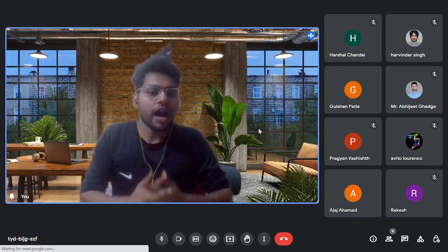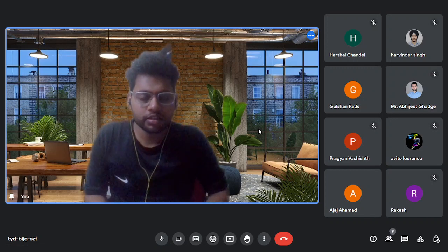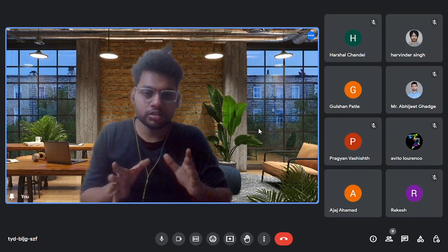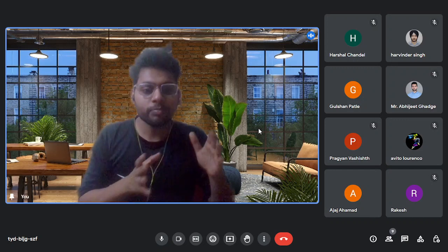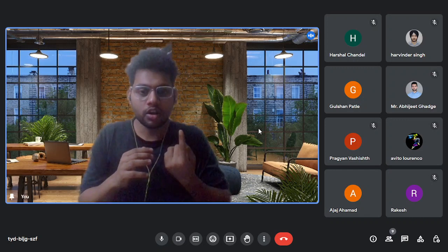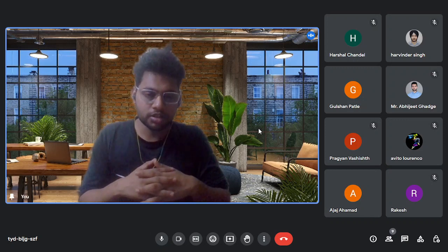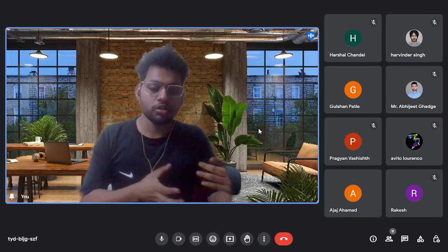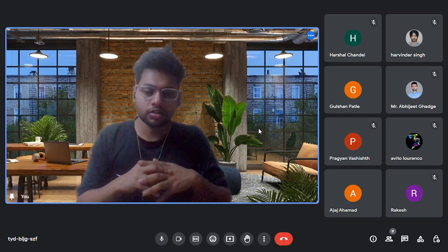Let me also explain. When a body is wholly or partially submerged in a liquid, in a fluid, an upward force acts on the body, and that upward force is known as buoyant force, as per Archimedes principle. Buoyant force is rho Vg. Rho is the density of the fluid, V is the volume of the fluid displaced, and g is the gravitational acceleration.